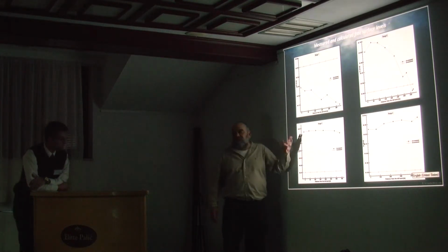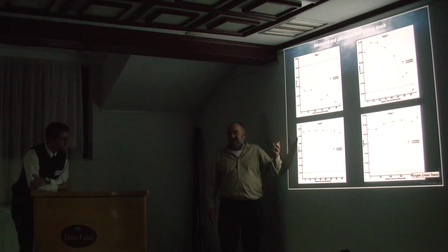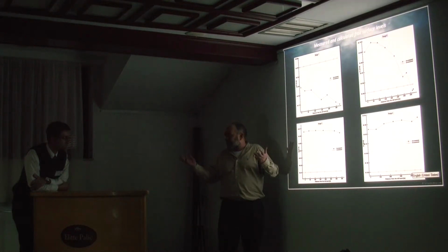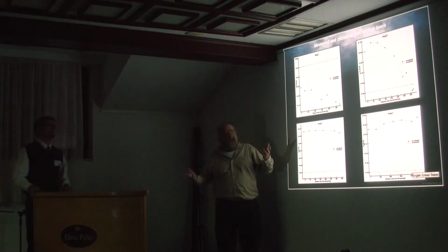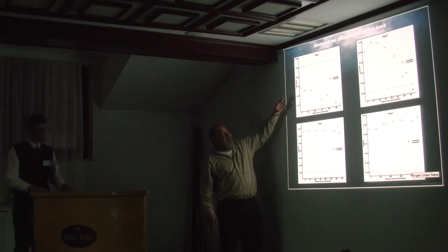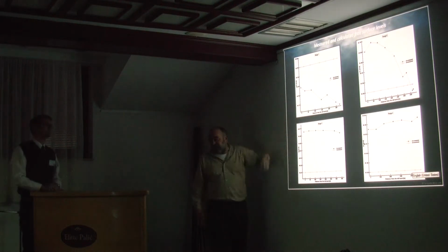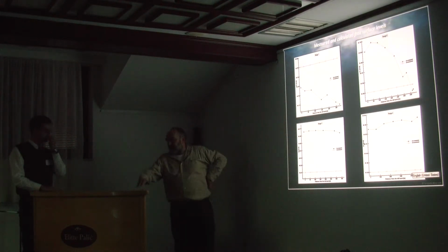So what we are talking about here is we have agreement in 2D free surface elevations and measured elevations at the same scale as with the 1D model, 3-4 centimeters, even better than the 1D model. And we see the change of free surface elevation is not actually horizontal.